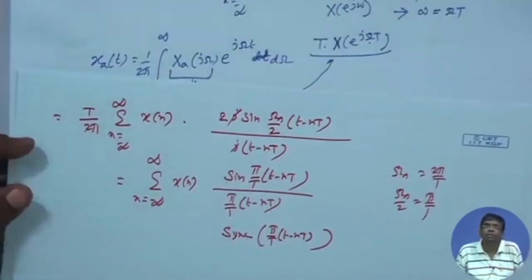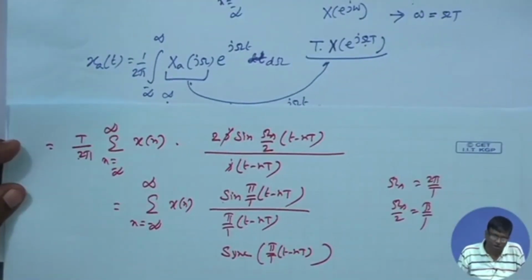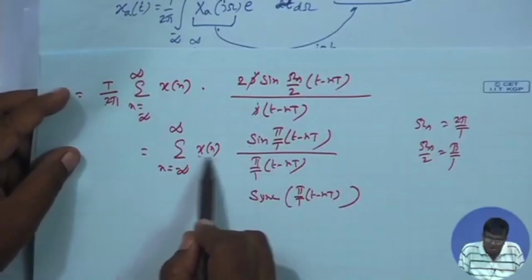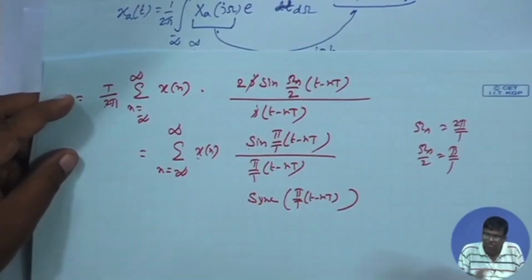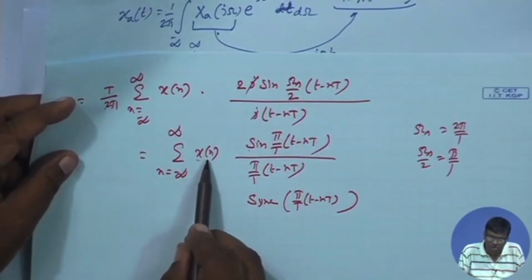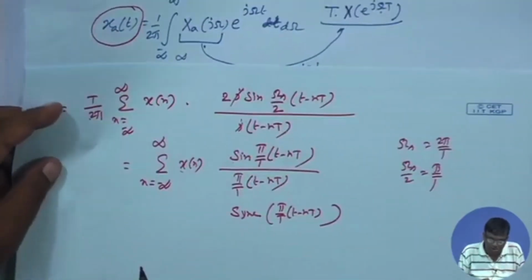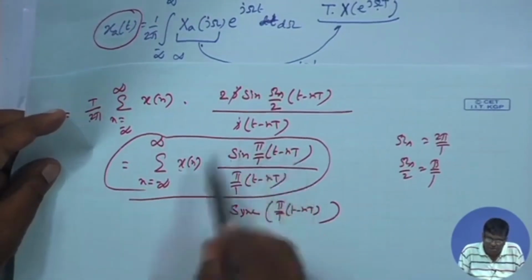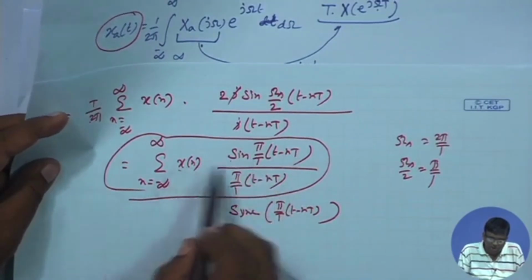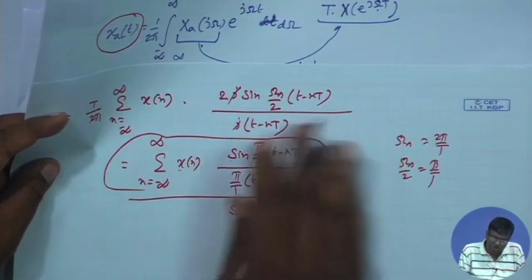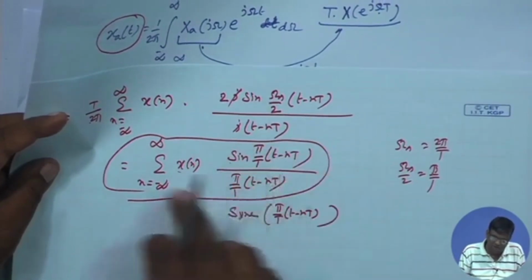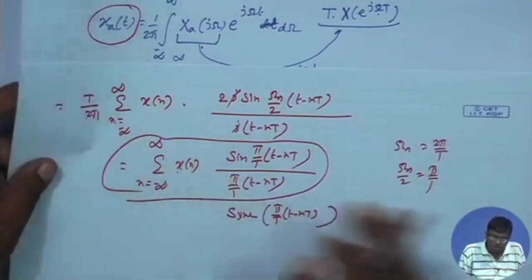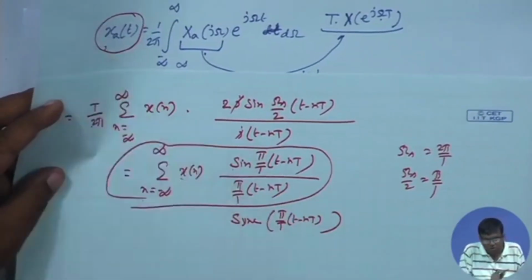So, if the function is band limited, and it is sampled following Nyquist theorem, then from this sequence, the samples, because you are sampling, you are getting a sample train and that forms a sequence. So, from the sample values you can get back a full original signal, analog signal, just by this summation. Okay, these are fixed functions, and when n equal to 0, so x 0 into just sin pi t by capital T and pi t by capital T. Then x 1 delayed version of that, x 2 further delayed version of that, and they get superimposed, and by superimposition you get a function of small t which turns out to be x a t.